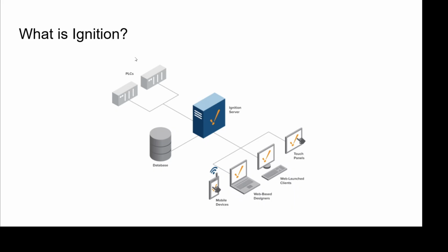But be aware that a programmable logic controller, or PLC, is effectively the brains that operate the plant. You can operate a facility without a SCADA system. So a PLC could exist on its own, and maybe there's some push buttons and things that an operator can use to start and stop equipment. But tying a PLC in with a SCADA system gives you a lot of flexibility to be more intelligent about how you're running your process, collect historical data over time, and basically get a good picture of how your facility is running and allow your operators to control that.